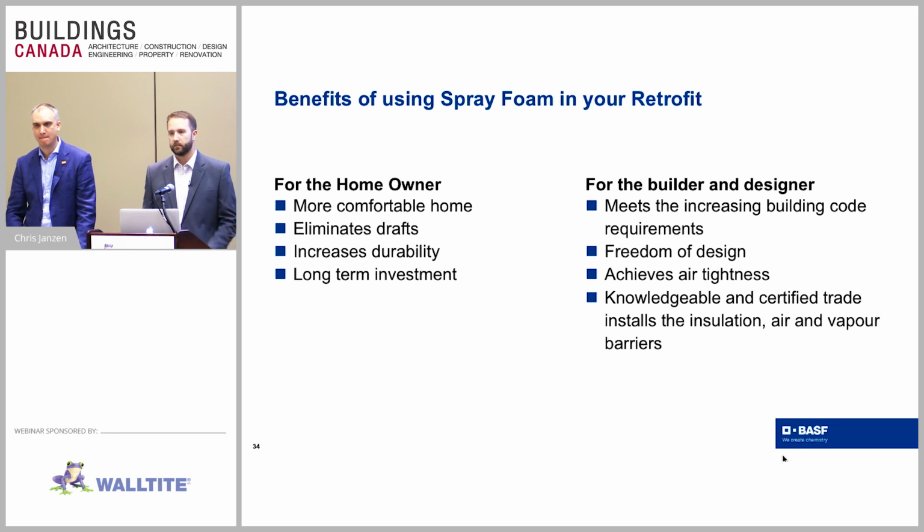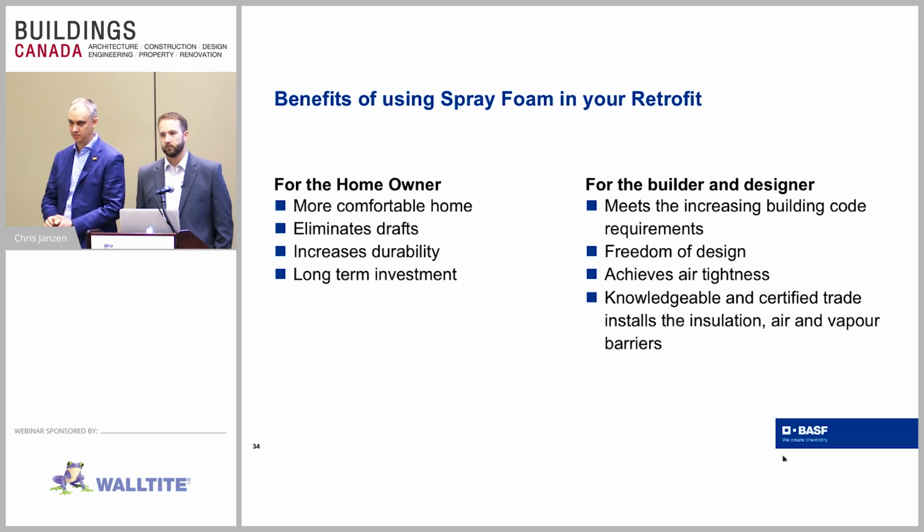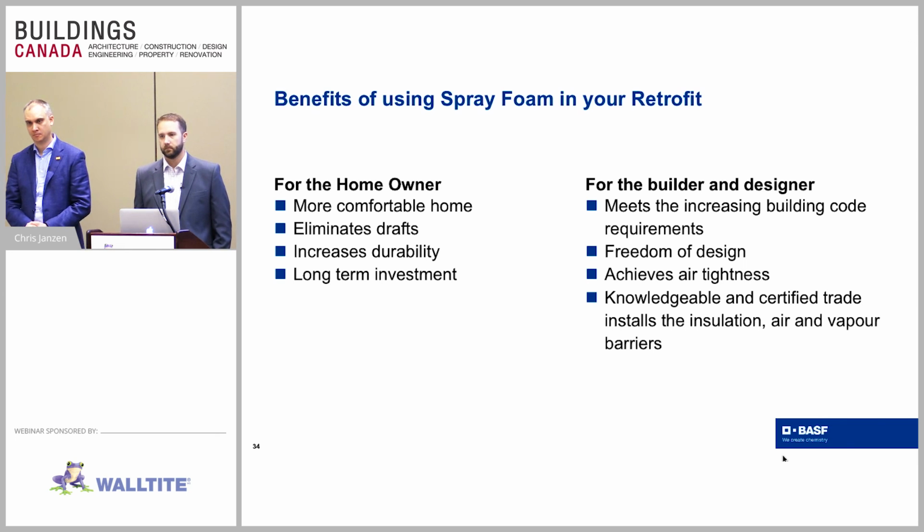With respect to sub-slab application, I've done some reading, and some of the building science guys are saying that the air between the gravel kernels or stones is about 99% humidity. Would you still recommend a vapor barrier being used with the SPF?